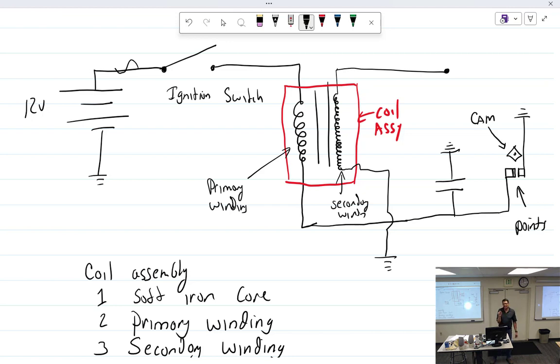And believe it or not, it's not putting out that much voltage. You don't want to touch it. It's going to hurt because it's going to be at least 1,000, I think 2,000, maybe 5. But it's not much of a spark. You can see it on gas stoves. Why is it not much of a spark? Because when it goes in the cylinder, air is an insulator, and the piston is compressing all that air. So you're actually packing air molecules around that. So electrically, that gap looks about 5 millimeters. Oh wow! So the denser the air, the harder it is to jump across.